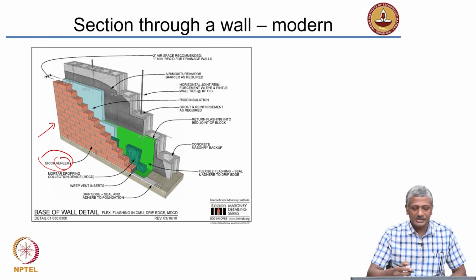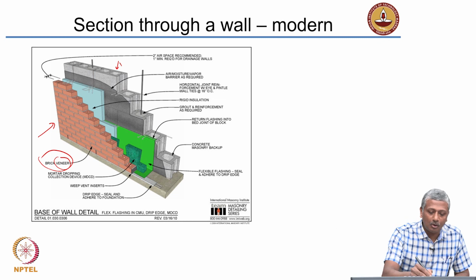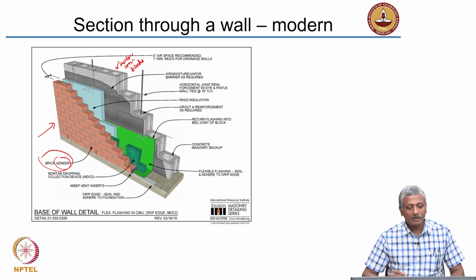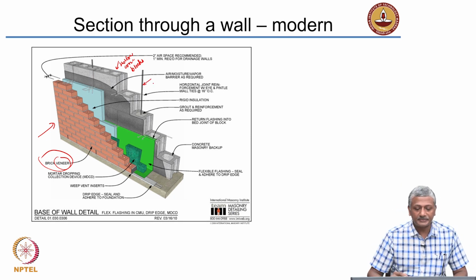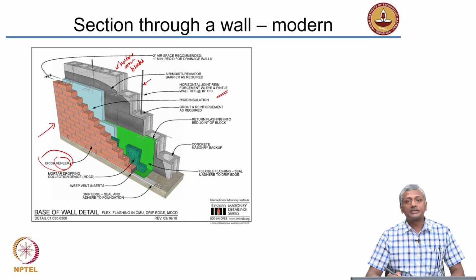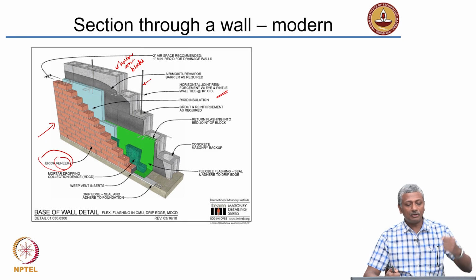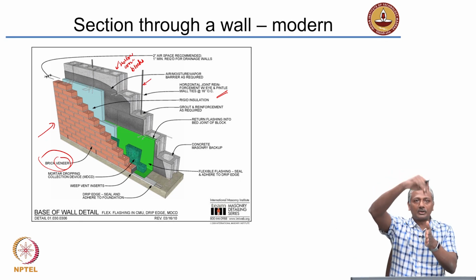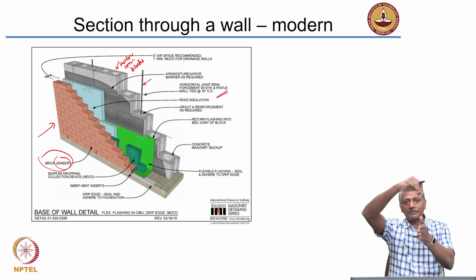But the actual wall itself is made with concrete blocks. These are hollow concrete blocks. Okay. Now interestingly, the hollow concrete blocks are also filled up with reinforcement. So hollow joint reinforcement is present in every 4 cavities that is there. So what does the reinforcement do? I told you that the walls are designed to take axial load. That means the loads that come in the plane of the wall.